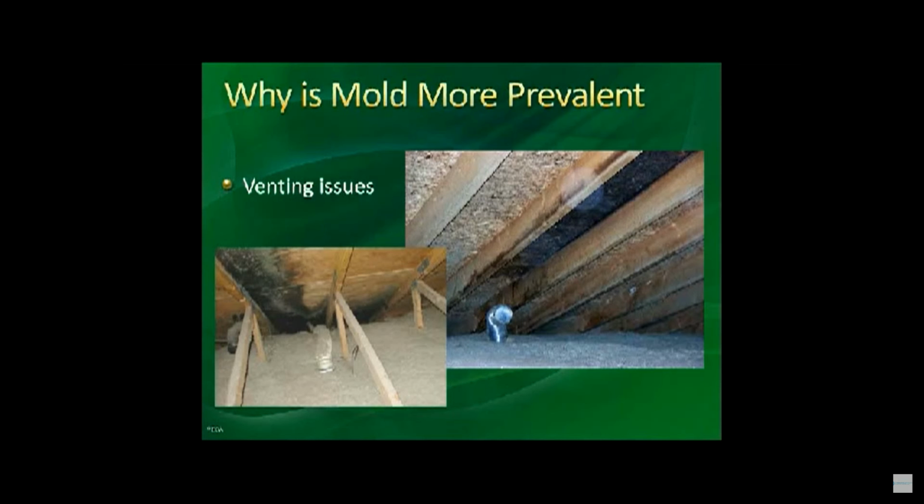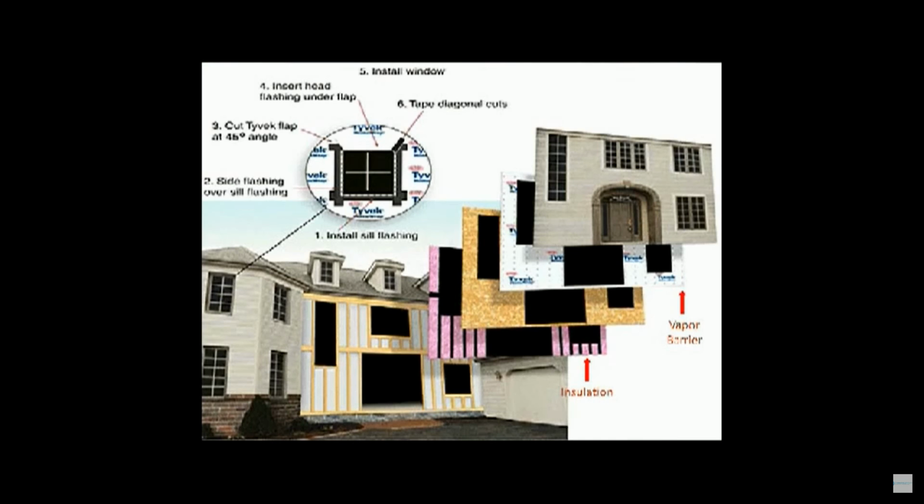As you see from a standard build of a house, as new construction is done and performed, and for those that do pre-inspections as houses are being done, they leave the particle board out to the weather elements. It gets rained on. Then they wrap Tyvek around it and seal the mold in. You have to watch for those as well.